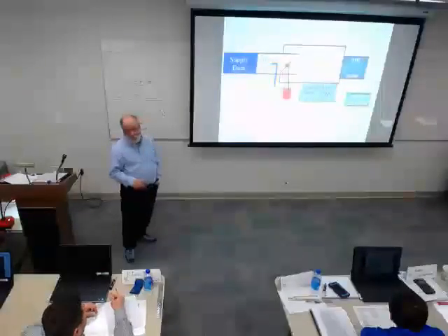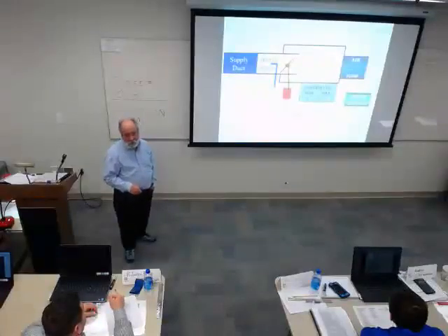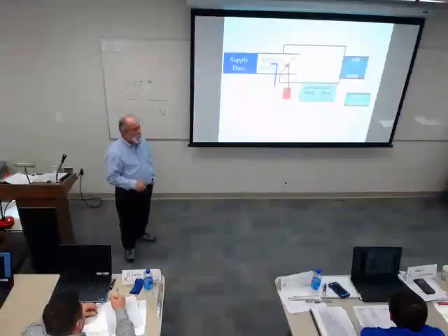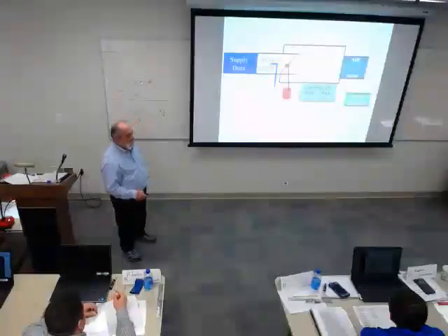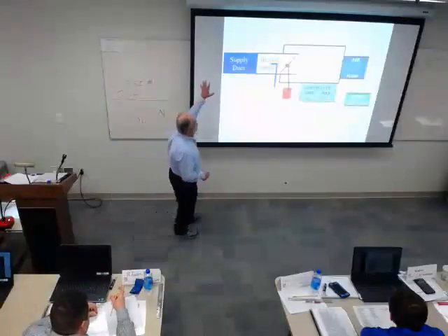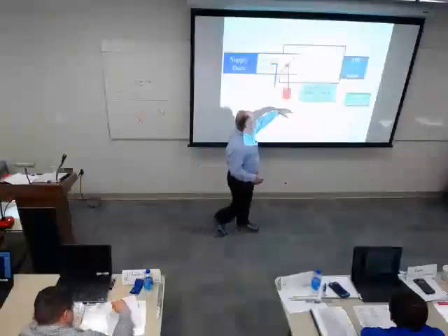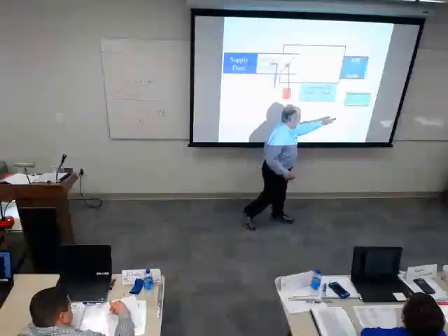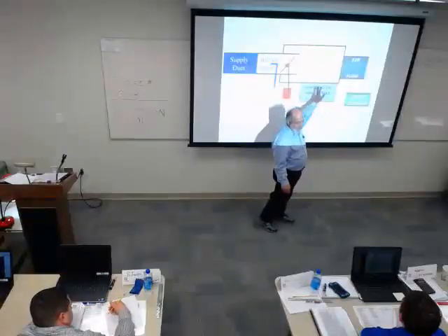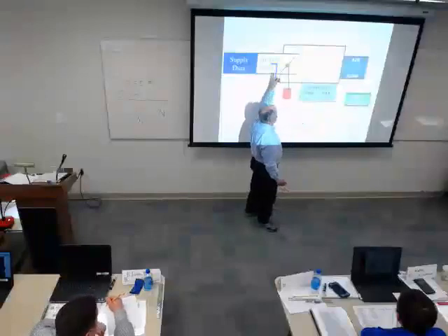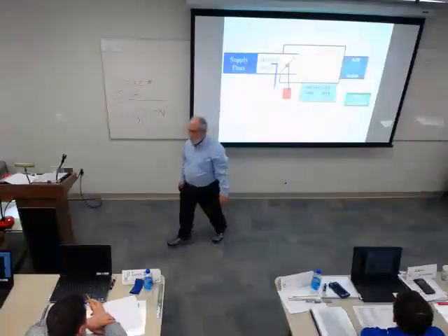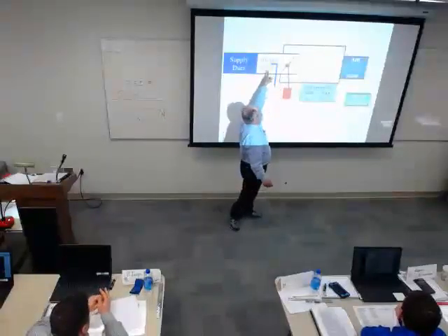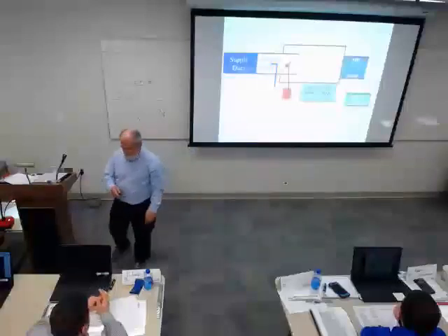If we had a velocity sensor, now we can control velocity, and if we know how much air the space needs at any load, all we have to do now is control the velocity. So it doesn't make any difference what the pressure is out here, or what the pressure difference across the box is. This damper is going to be changed in order to maintain a velocity there. So we get temperature back here, and it tells us what we need for heating or cooling. That information is used to determine what velocity should be seen here. Now you can have pressure changes all over, and this damper will change in order to keep that velocity what it's supposed to be for that condition. That's pressure independent.